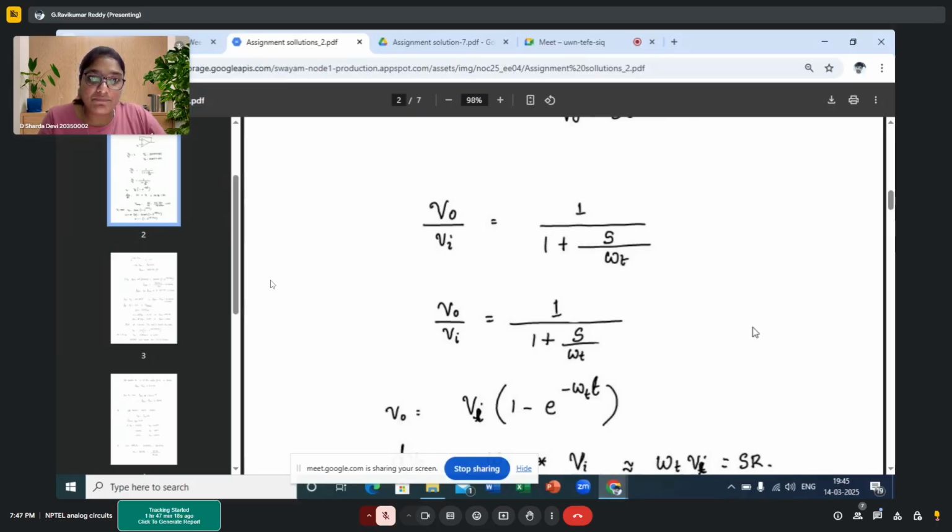We can write this for an exponentially changing signal, right, madam? More or less the behavior is almost similar, so that's why they must have translated it. But basically, you understand, right? For a step input, you would never get an immediate step output. That is never possible. It will slowly rise, and that rise may be parabolic in nature, ramp-like, step-like, or exponential. It all depends on the circuit that you are using. So here the behavior they have considered is that of a simple delay model. 1 minus e to the power omega t is actually a simple delay model, like a basic normal delay.